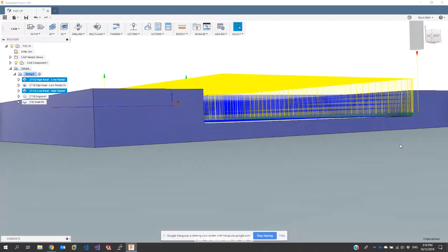high-speed clearing. If you watch YouTube and you look at adaptive clearing on a high-speed milling machine where you're doing maybe 8 to 10 meters a minute with full flute length depth of cut, on a machine that's very rigid, that's all well and good, but where you can't do that, you shouldn't find too much difference between the two different strategies here.